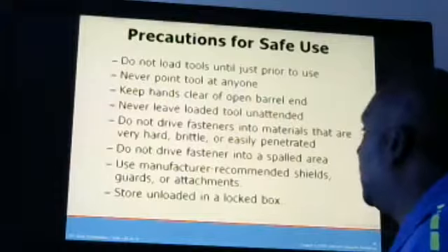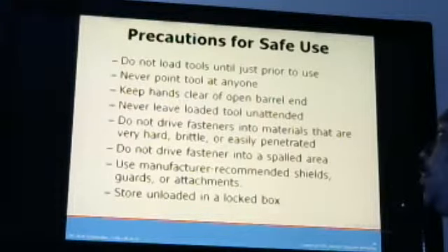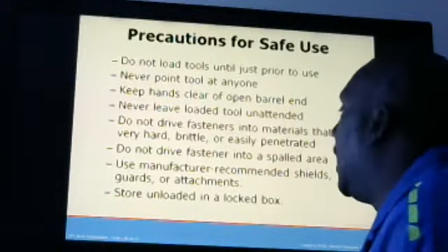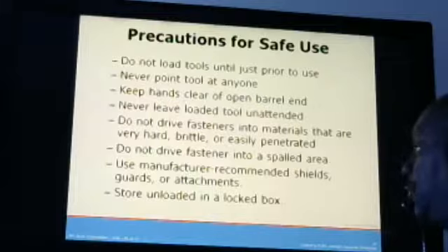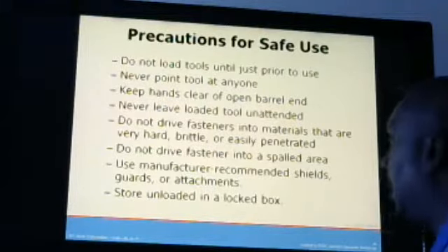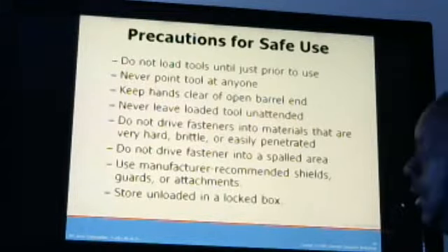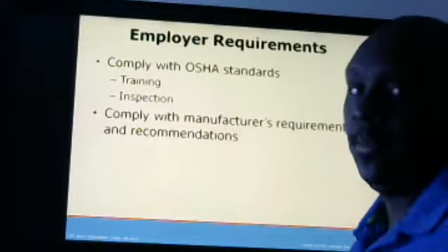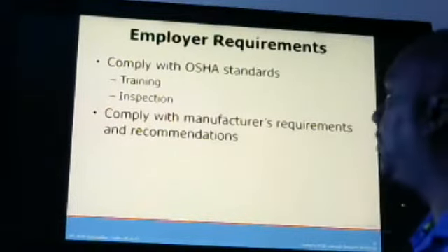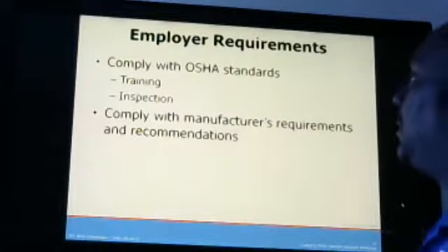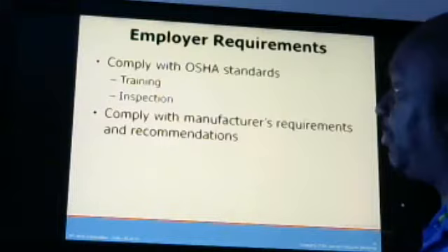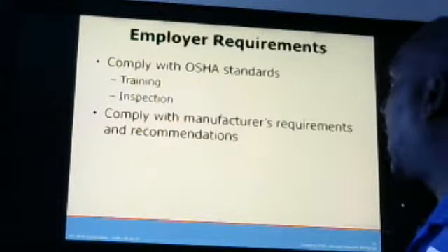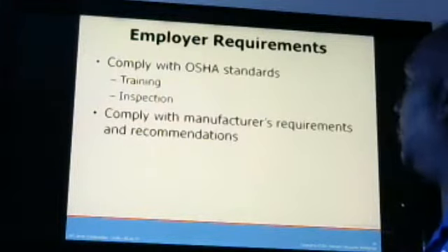Don't drive fasteners into materials that are very hard or brittle or easy to penetrate. And do not drive fasteners into spalled areas. Use your manufacturer's recommendations for shields, guards, and attachments. And always store unloaded in a lockbox. All right, so the employer's responsibility requirements are to comply with OSHA, make sure that training takes place, that inspections take place, and comply with the manufacturer's recommendations.